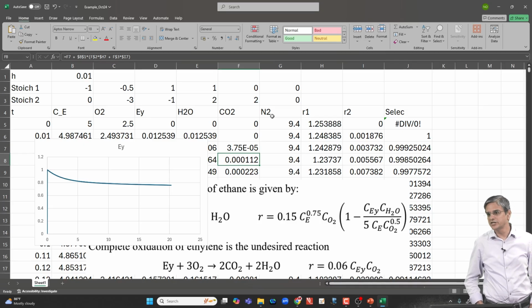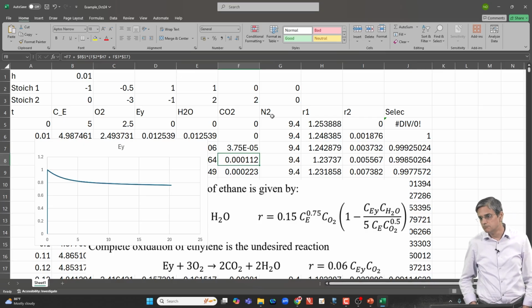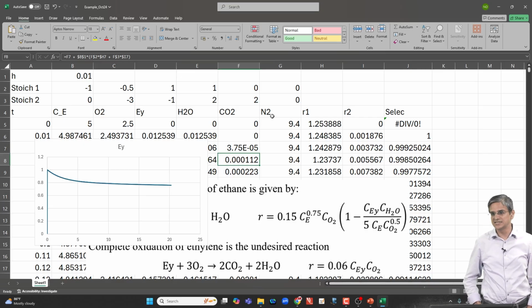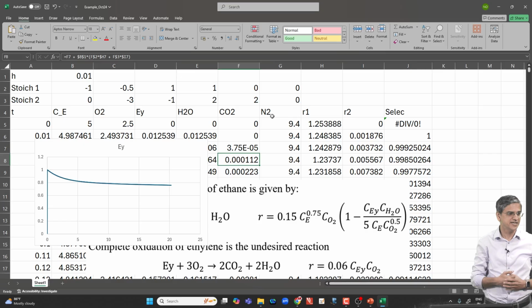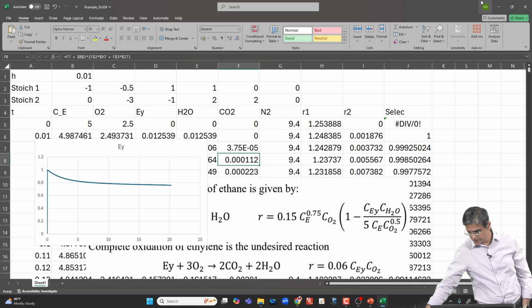There is no reason to necessarily say that in a problem like this, maximize the concentration of A or B or C or D. It could be maximize concentration, maximize selectivity, maximize yield, minimize the waste, minimize energy input into the system, any of those cases. What you want to optimize on goes in the numerator, what is the handle that you have goes in the denominator in df by dx. All right, so that is what we have for today, and I will see you on Monday.